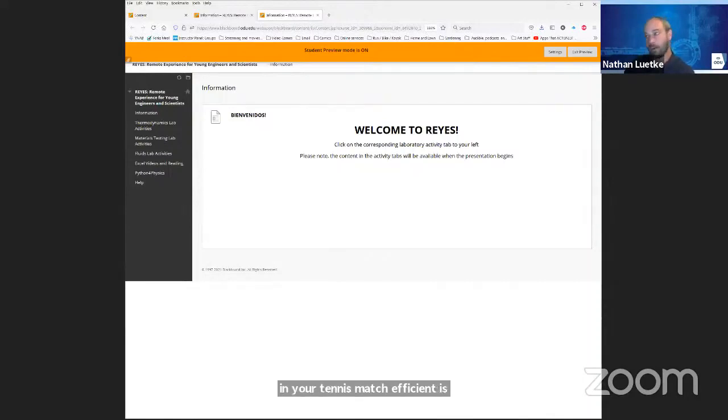We cannot make a Carnot engine because the Carnot engine is composed of 4 reversible processes. We have isothermal heat addition, isentropic expansion, isothermal heat rejection, and isentropic compression. Isentropic processes are, in thermodynamics, well, not all isentropic processes are reversible, but all reversible processes are isentropic. You know, that's a question you might see on the PE exam one day if you take it. But the point is, we cannot create that.